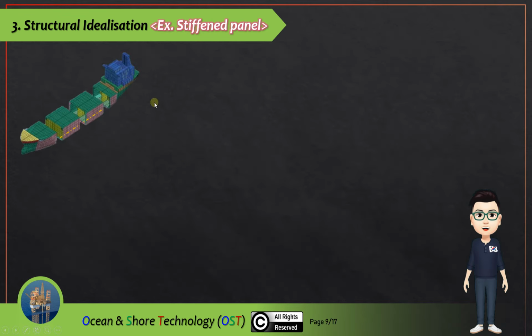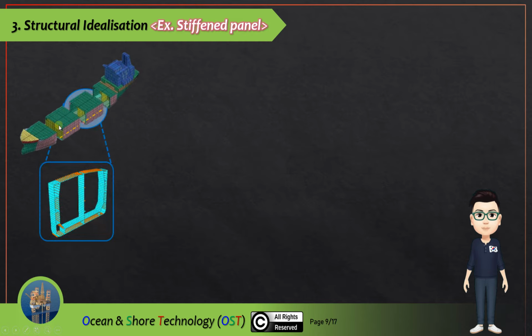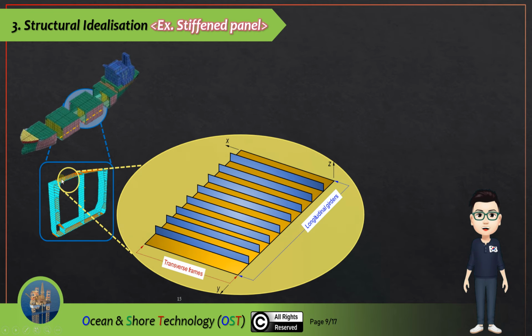So this is the typical shape of vessel ship structures. And if we focus on the midship section, this is the one, the frame spacing is about 4 to 6 meters in length here. And I will discuss the stiffened panel. So of course we will focus on the deck area. So this is the extracted stiffened panel. This is the combination of the plate and the stiffener. In this case, this is the flat type.